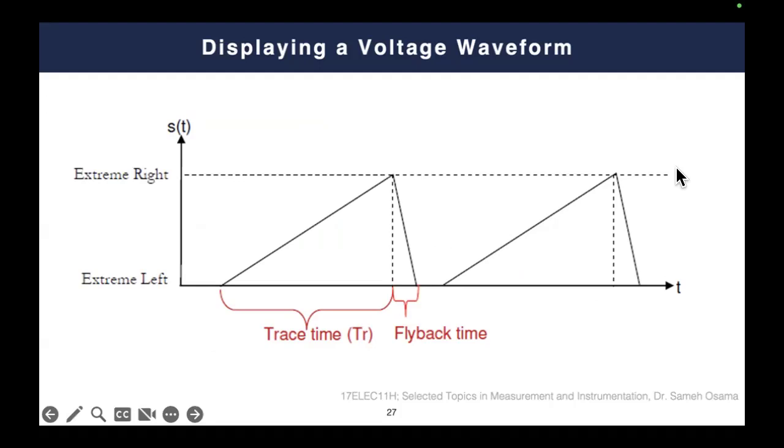We have to have our sawtooth, between quotation marks, the triggering signal, to be in a periodic way, which is, of course, no problem. We can make a generated sawtooth signal, and we can make it periodic. This is no problem. But herein, we have a very important feature, which we call the flyback time. Because simply, a hypothetical sawtooth signal will say that, okay, this point will drop to this, and we will start a new sawtooth. But this is hypothetical, because you know in your background that there is nothing called instantaneous change.